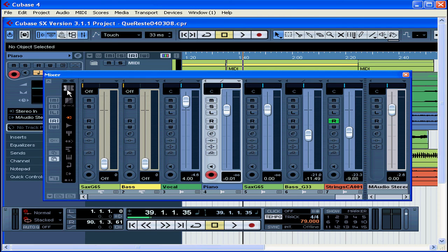The Command Target tool is a very interesting feature. If you want to exclude input buses from your key commands, enable the left portion. If you only want to apply key commands to selected channels, enable the center button. To exclude output buses, enable the right button.